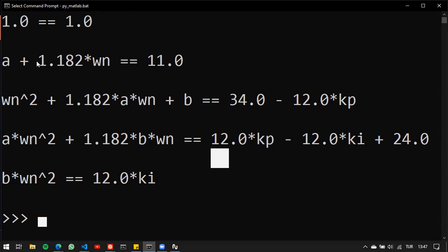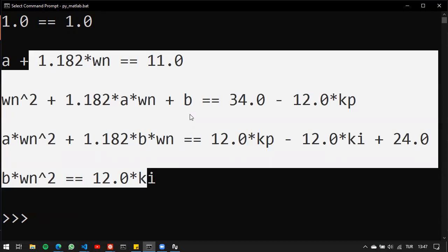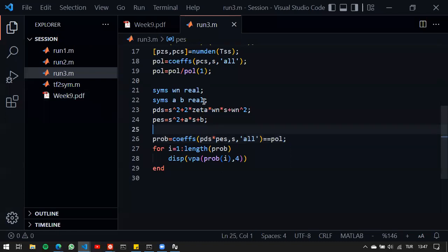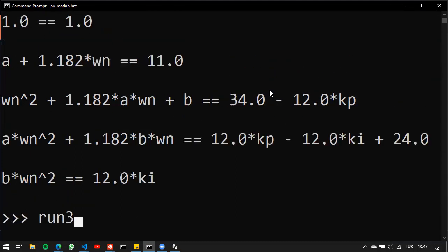Now we have 5 unknowns. What we can do is just go ahead and use omega n maybe as the free variable, and then try to design a controller. But for the sake of simplicity, just for this example, I'm going to pick omega n so that it works, because that's not really the point of our discussion here, just to cut it short. But usually we have to choose one parameter and look for maybe a tabulation or maybe a root locus method here. But I'm going to skip that part. So let's maybe, for example, assign omega n equals 1 and try to look at the problem.